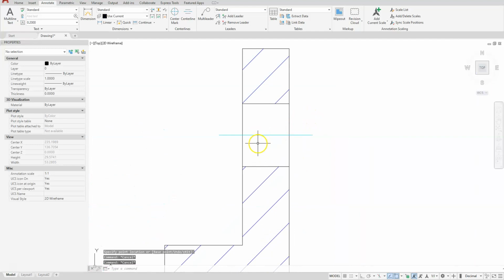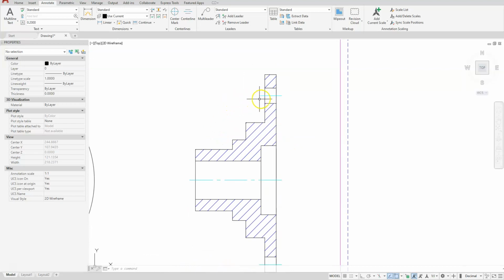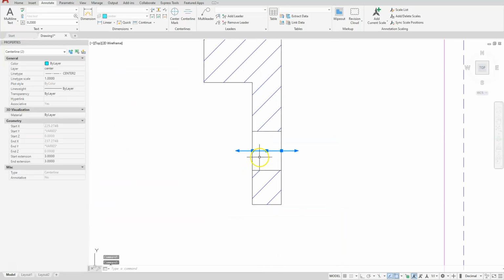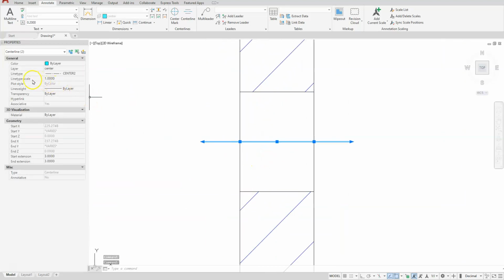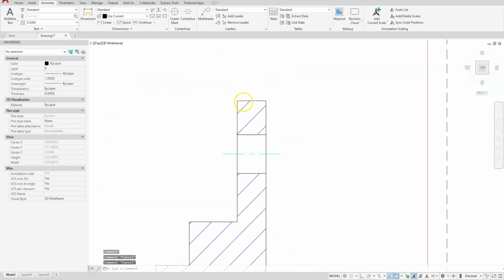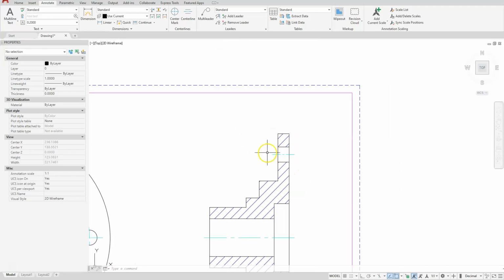Okay, to adjust these lines, it's really typical that you do see the dash in between them, and I know in the drawing that it does not show that. So I'm going to select this line and the bottom one as well, and zoom into the bottom. The linetype scale in here is going to adjust them just for those two lines. So I'm going to change them to 0.75. I'm still not seeing it. Let's take a look at 0.5. You can see that that gap does appear. Just hit escape twice to get out of that. And you can see on both of them, I do have that center line with the dash in them going right through.